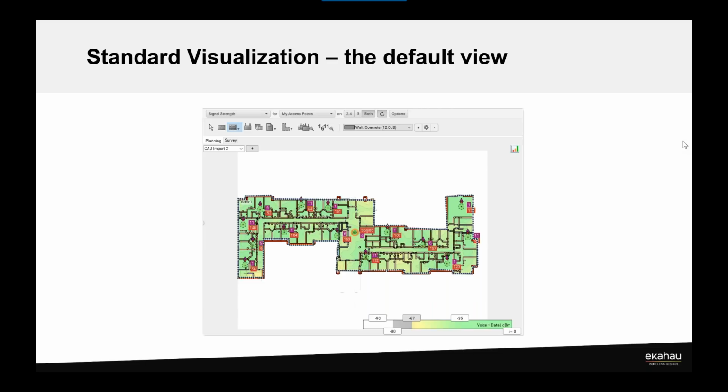And if you've ever really looked at received signal strength indicator values as determined by different clients, you'll know that they're not always the same. There's no industry standard for calculating RSSI values. There should be, but there's not. Every chipset maker can determine how they want their chipset to interpret the information received, whether it's raw energy or data, and look at the signal strength and calculate that themselves.